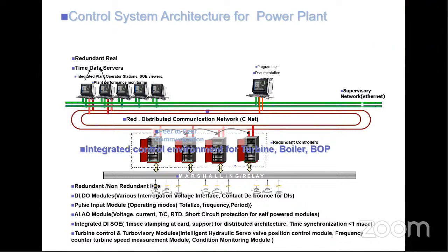Right, sir. So you were saying that from the HMI, a bidirectional communication can be done from the actuators through your DCS node up to the ES or the HMI, and from the HMI through the DCS nodes to the marshalling relay, and from there to the actuator. The green lines you are showing are the supervisory network, Ethernet and all, connected to the server, and from the server through physical wires we connect to the DCS nodes, the red lines. These red lines are digital signals, right, sir?